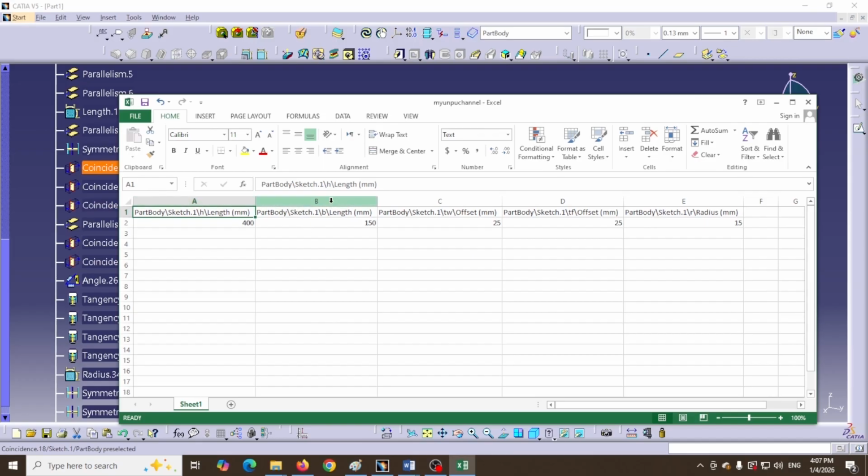Important note: you must never swap the positions of the columns. If you do this, CATIA will not be able to read the columns it created. Therefore, you must select dimensions in the correct order at the beginning in the Select Parameters window.